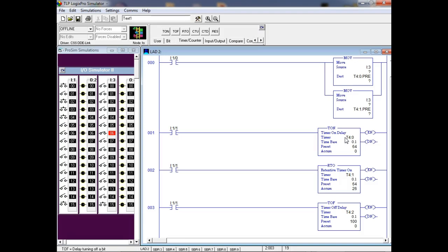And so we did that in our class last semester. The guy gave us a logic diagram that I realized right off the bat could be reduced. And when we reduced it, we realized that one of the switches wasn't even required. So it was a 3-switch circuit, right? You understand that? And then when we set up the Boolean equation for the circuit, I just showed the class what the power of Boolean algebra is.